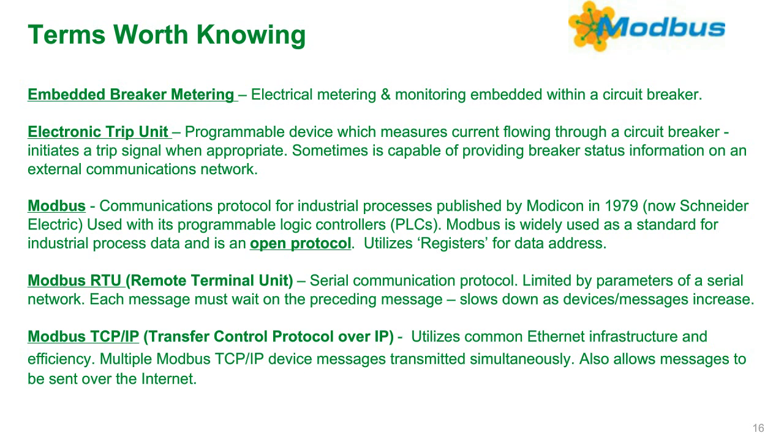And with a serial protocol, you're dependent on each message being sent and then received back. So you send out a request and you receive back the answer, and then if that happens, you send out the next request, that next answer comes back. So you have kind of this chain of messages that are waiting in line. And as you get more and more Modbus serial devices on a network, that message time gets longer and longer and longer. So there is some limitation on Modbus serial of how many devices can go on a network and the effectiveness of that network as it gets.